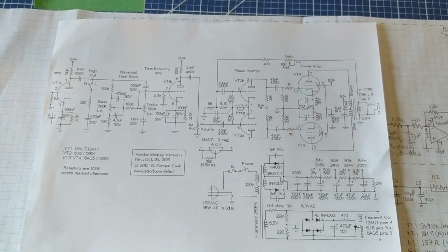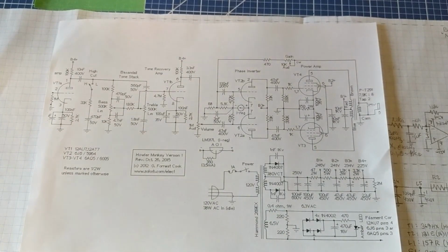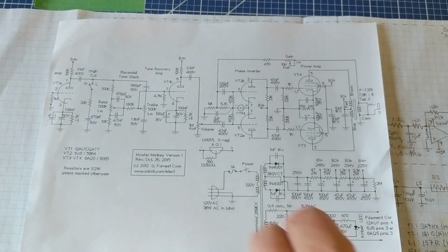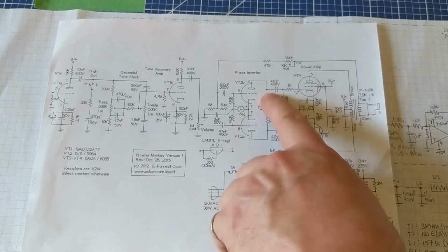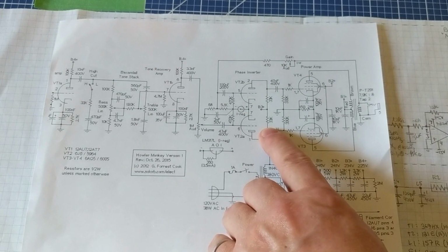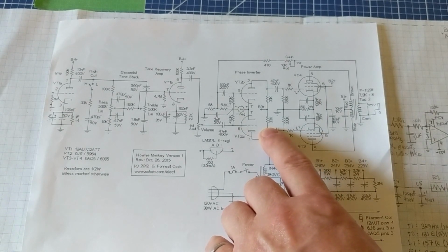From this, I took some design concept ideas for the phase inverter and for the push-pull 6KQ5 outputs. Mainly what I was interested in here was his usage of a constant current source for the long tail differential pair forming the phase inverter. Notice that the design is a phase inverter, not a phase splitter, and I'll go into the differences between the two in the next document.